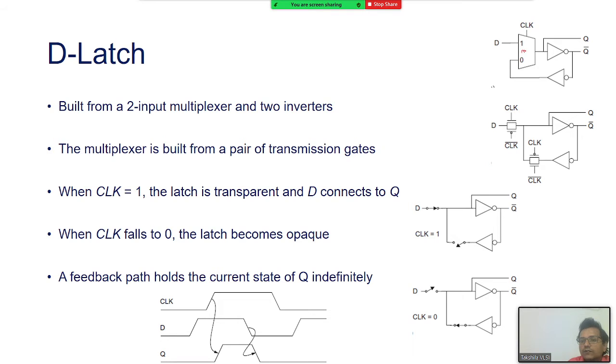I know now this is my multiplexer, right? A 2:1 multiplexer. So there are two inputs, one is here and the second is here. I know that this multiplexer can be implemented using pass logic or a transmission gate, right? So I have that understanding. Now to this 2:1 multiplexer, I have a data input. That data input can be held to logic 0 or logic 1. And I have a special input or special control that is called the clock. So when the clock is 1, I say that the circuit is active.